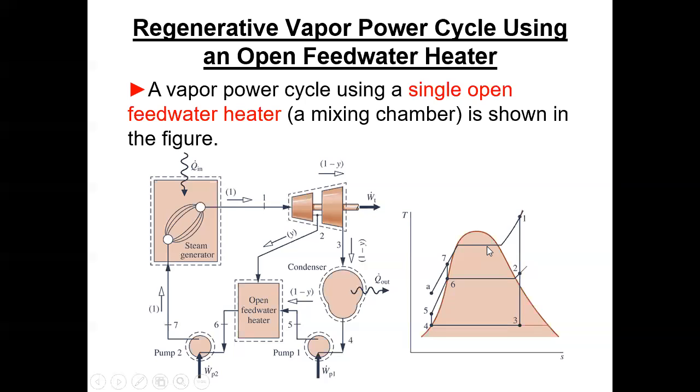But we're getting an increase. But we're reducing, I guess, the rate that we have to put heat into the boiler, because the boiler is the main generator of irreversibility. So we're making the boiler do less. And so proportionately, we come out better in the wash between the decreased work, but the decrease of boiler heat input is greater, and so our efficiency goes up.